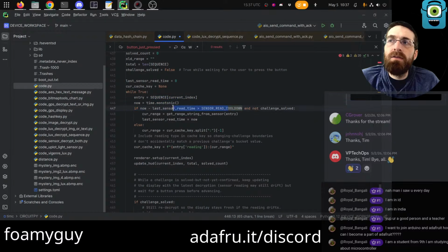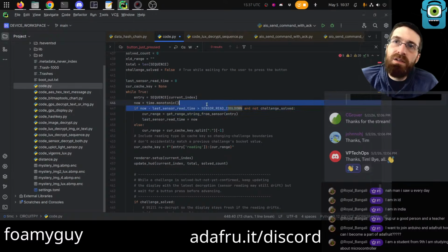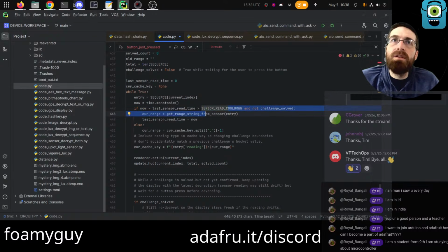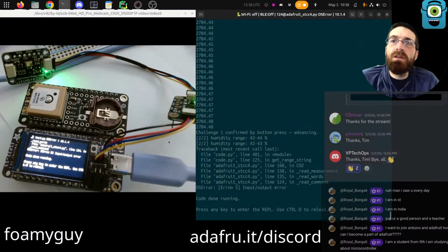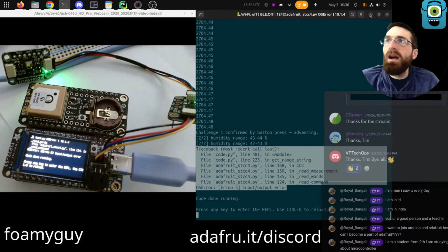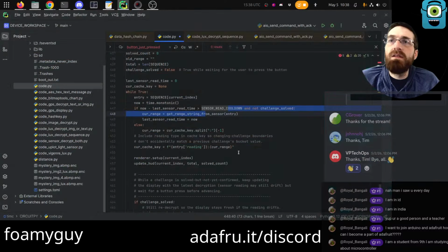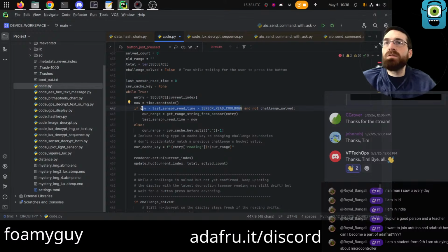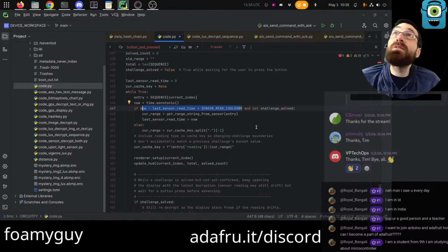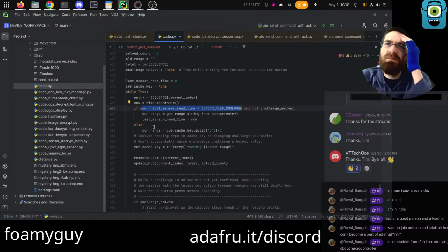Oh yeah, okay. This is coming back to me. I was thinking kind of unrelated, but if we look back here, this might be crashed, right? Yeah, this is crashed right now. I think that's because this sensor does not like to be read too quickly. I actually added this cooldown to try to resolve that, but I think what I need to do is also try/catch. Maybe the driver should raise. I don't know. In any case, in this code, we need to handle it.